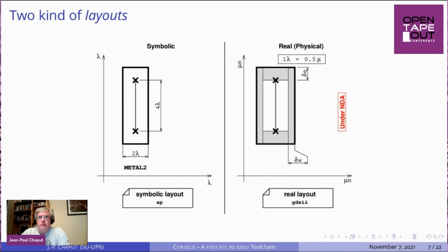So it ensures portability, because even if you have an open PDK, completely free PDK, when you change PDK, or target nodes, you still have to redevelop all your standard cells and all your design, especially in digital. So it's costly. With Symbolic, you can hope to not do that. Just develop once and then port to every technology.